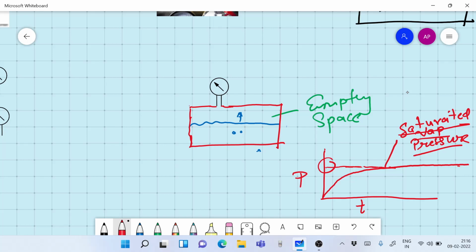So we come to an equilibrium, and therefore at the equilibrium the pressure we read is the saturated vapor pressure, and that is commonly known as vapor pressure. But please understand that whenever anybody is talking about vapor pressure or giving you a value of the vapor pressure, he's in all probability giving you the value of the saturated vapor pressure, because you have data of the saturated vapor pressure itself available.